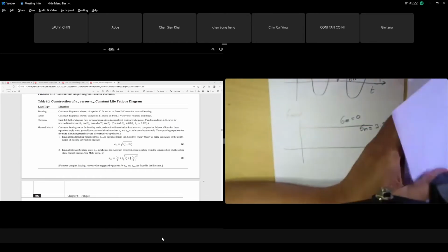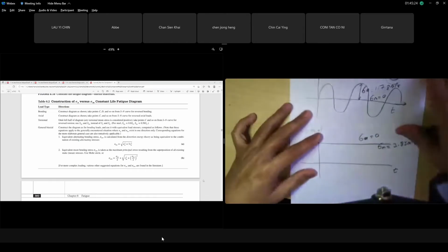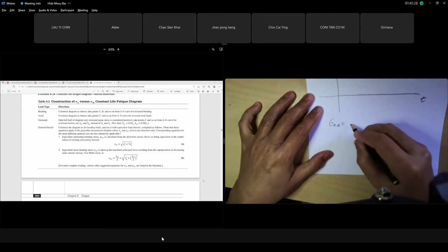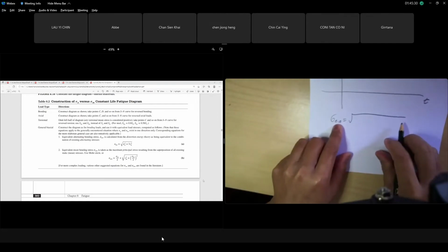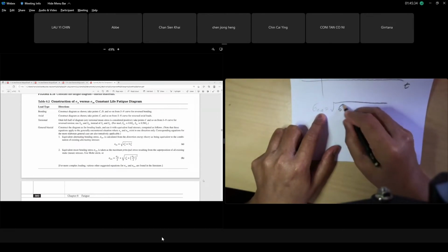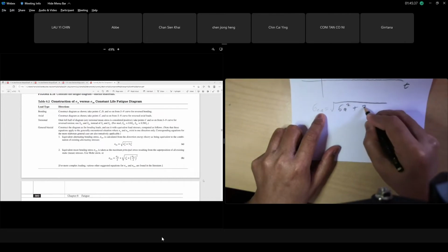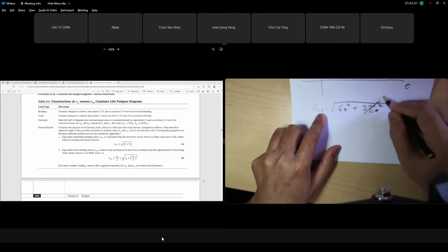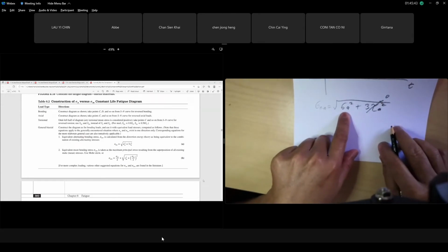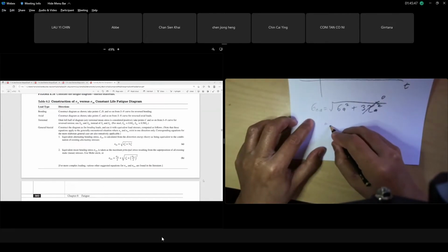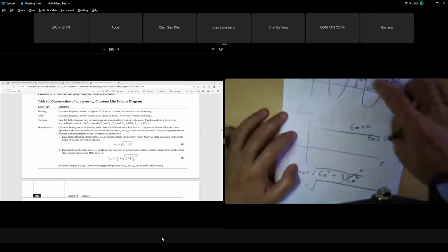Where is the equation from before? So the equation that we have, okay, now sigma EA, because for EA we need to find the combination, the equivalent stress alternate, equals square root of sigma alternate square plus 3 tau alternate square. Okay, since we don't have torsion, of course this one is zero. But what about this sigma? We have two cases, right? What do we have as sigma alternate here? What has alternate? Axial and bending.